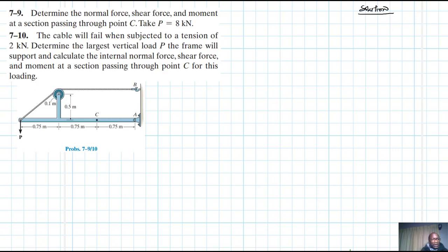We are going to section this cable here, okay? And we feel here the problem will be much faster to work on. You could section it here, but once you section it here, it means you need to take care of the forces that are going to be imposed here by the cable, right? So you'll have more work, okay? And yes, it's important to intelligently section the cable at a point that will make your work much faster.